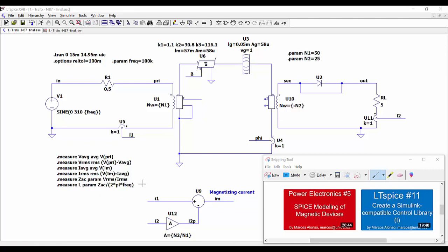Of course, these calculations are only valid when we operate in linear mode. This is without the rectifier diode, just applying the resistance to the output, but we can also use these calculations when we are using the rectifier to demonstrate that the value of the magnetizing inductance is going to decrease when we use the rectifier at the output.